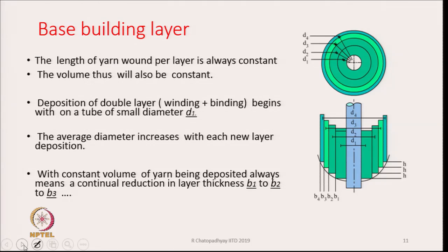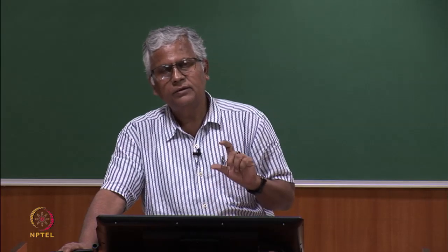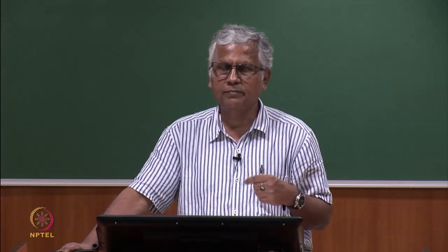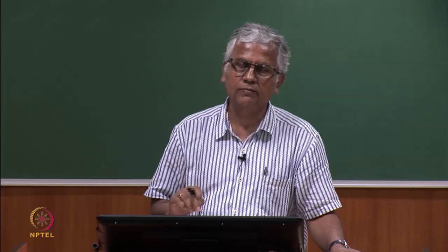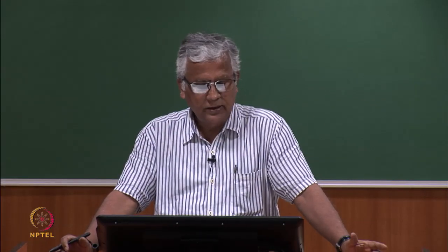For every cycle of movement, the rail takes the same time always, and therefore, during that time, that upward stroke and downward stroke, whatever length is being delivered by the machine, that is the drafting system, remains constant, that does not change. If the length remains the same, the volume of the yarn also will remain the same.